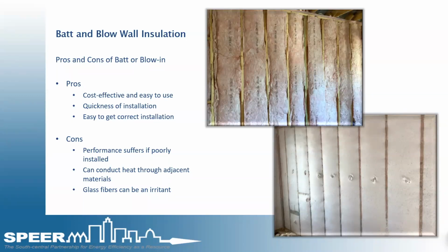But if you look at the insulation in the lower right-hand corner of the picture there, if the weight and density of that insulation is not correct, that will settle over time and leave gaps above that wall. It's very hard to determine, is it the right density? My team always pushed on it. If it pushed in and left a handprint, it's probably not a very dense blow.